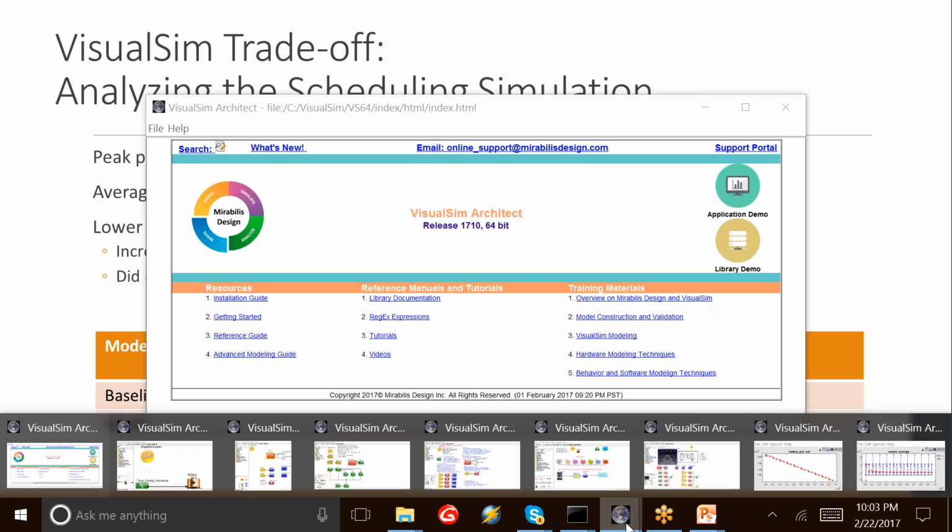Notice here, when I added the link back at 150, there's actually an even distribution of load, but the latency actually went up. So one of the things that becomes counterintuitive here is that even though I added the link, my latency actually went up, which tells me that maybe it's using an extra hop, an extra path as it flows through the system. So you can actually change the routing table midway and see the impact on power and the performance of the system as well.